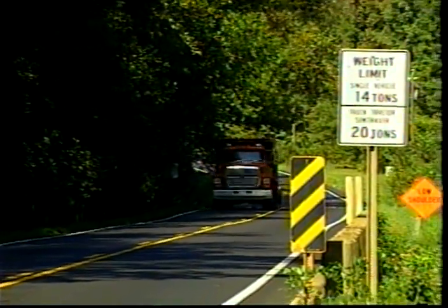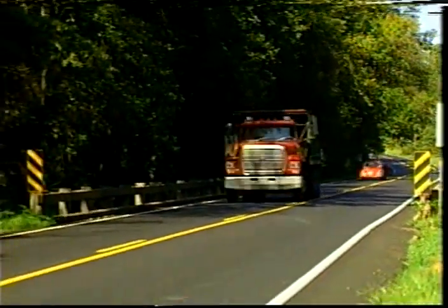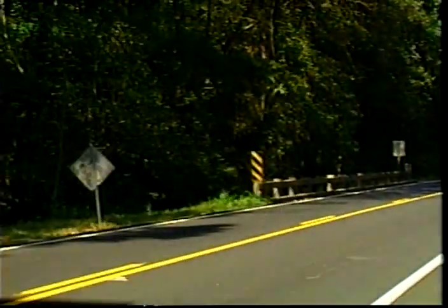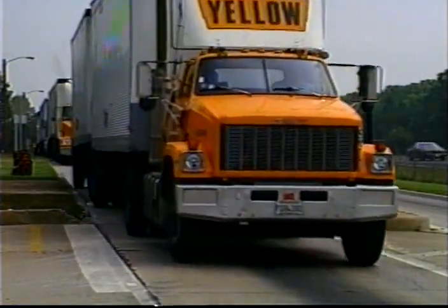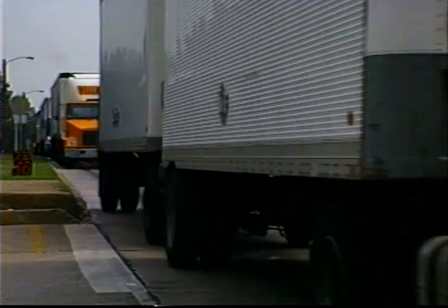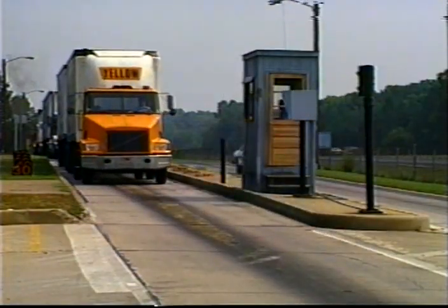Maintaining bridges that are properly posted and providing a controlled permitting process are critical elements in any bridge management program. Improper use of overweight permits, inadequate enforcement, and inadequate fines for overweight vehicles may result in fatigue and stress damage to bridges.